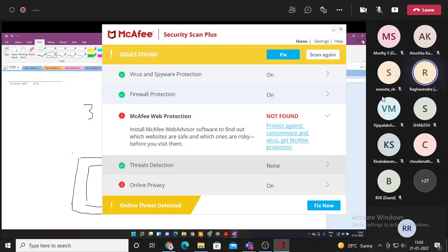So let's say this is the transmit USRP. By the way, I need to use a separate USRP for transmit and a separate USRP for receiving, because the daughter board present over here comes in two types. One can only transmit and the other one can only receive. So the I will be given to one SMA port and the Q will be given to another SMA port. Similarly, we have another USRP with a different daughter board, different as in the functionality is still the same, except that this receives instead of transmits.